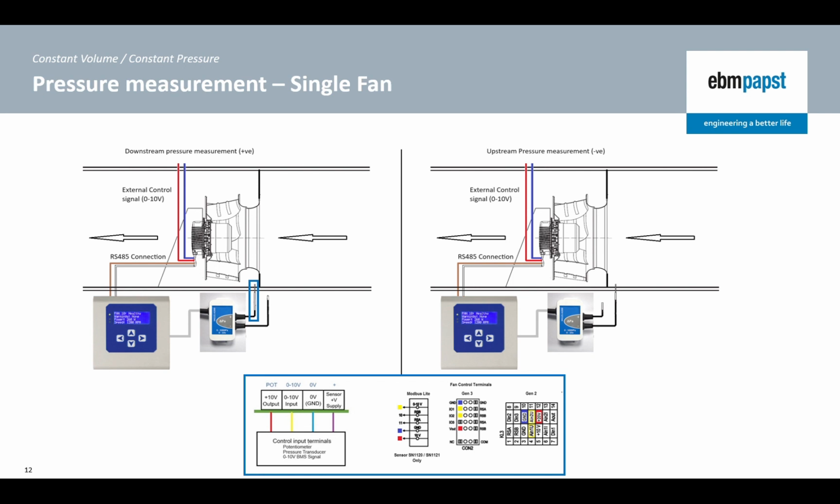In an application that requires containment of pollutants, it may be desirable to negatively pressurize the room or building and control the pressure upstream of the fan in comparison with atmospheric pressure.